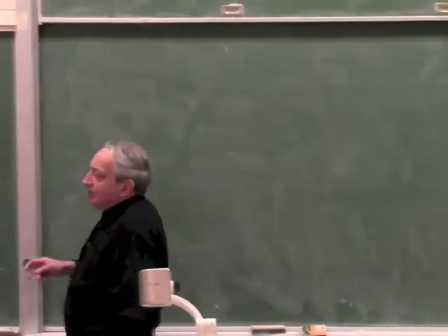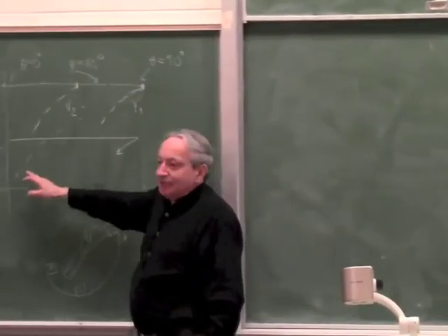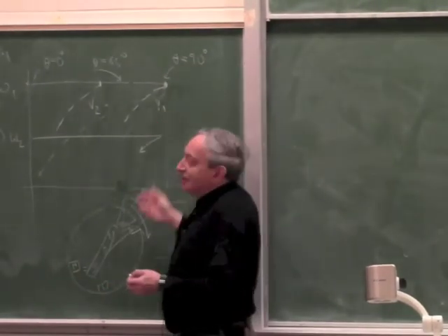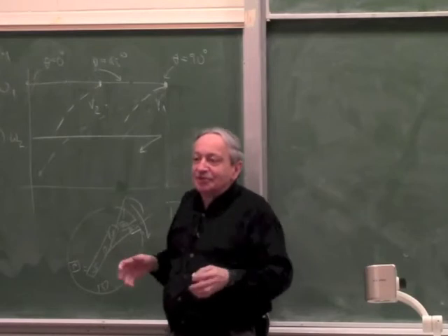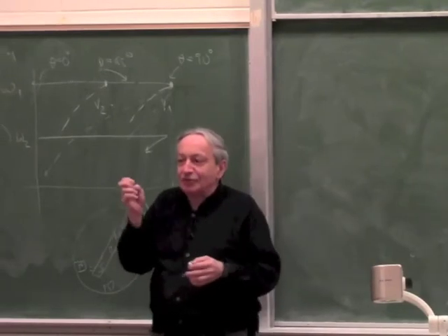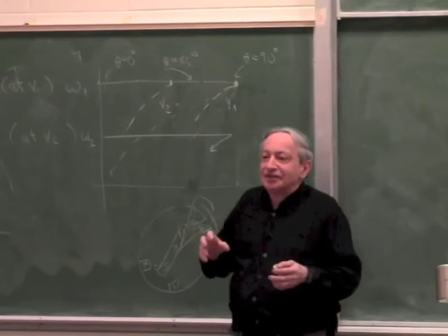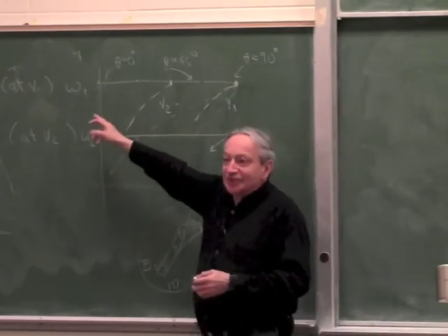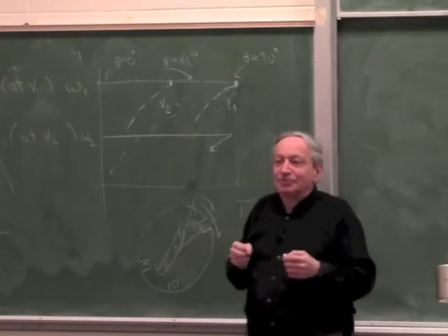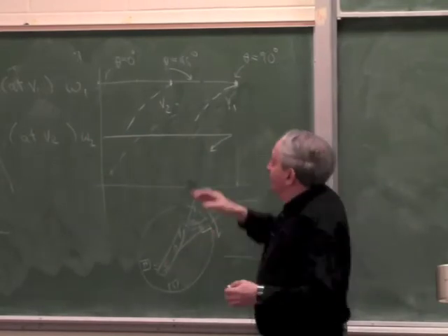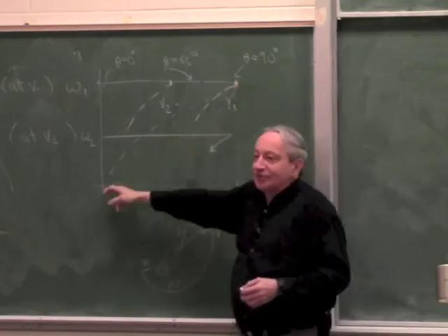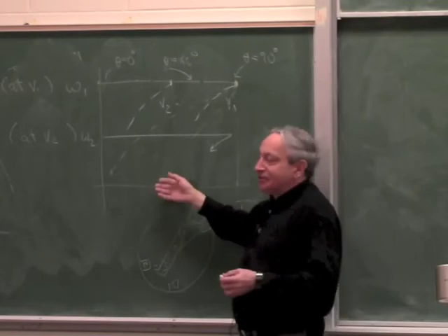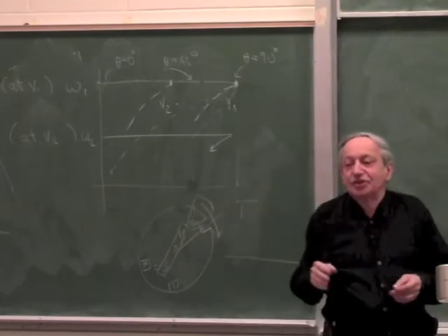Now, I'm reminding everybody, the reason why this is very undesirable is when you start a motor, you always exceed the rated torque. Because when you start a motor, there's inertia. So the very first few milliseconds, the inertia doesn't allow the rotor to move as fast as the rotating field wants. So when you start the motor, the first minute, there is always a high torque. So if this motor collapses at a high torque, it doesn't want to start with any inertial load. And that's, as I mentioned, the only disadvantage of synchronous motors.